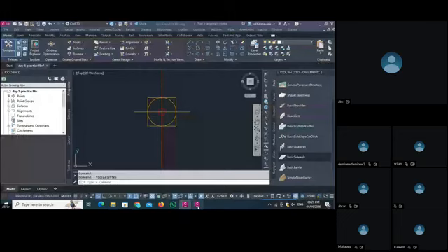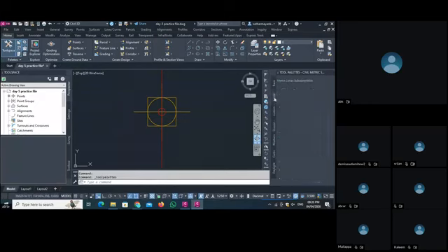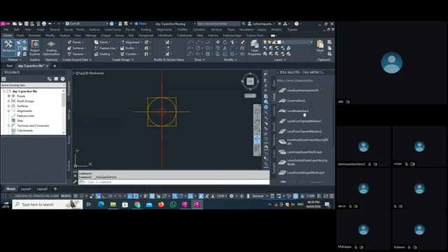So the last part that I want to show is this area. We have a different folder here. In the lane folder, you see the particular lanes, different types of lane. See, this is the crown lane. What is the crown lane? It means from the center there is a slope to both sides. In an uncrowned lane, you have a flat surface. So Civil 3D provides these different types of lane.